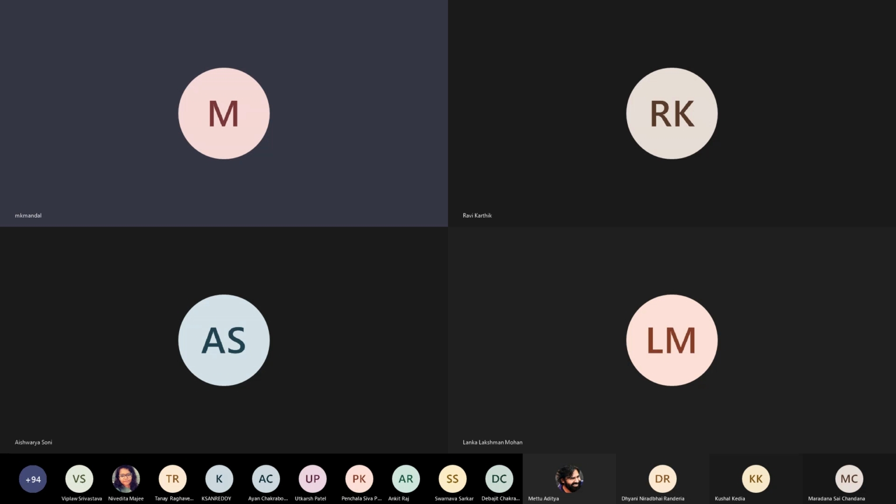So now from this electric field orientation, you can actually say how I should place this microstrip line inside the waveguide. So this is the strip, the microstrip line. Then I should have electric field component as much as possible in the same direction.